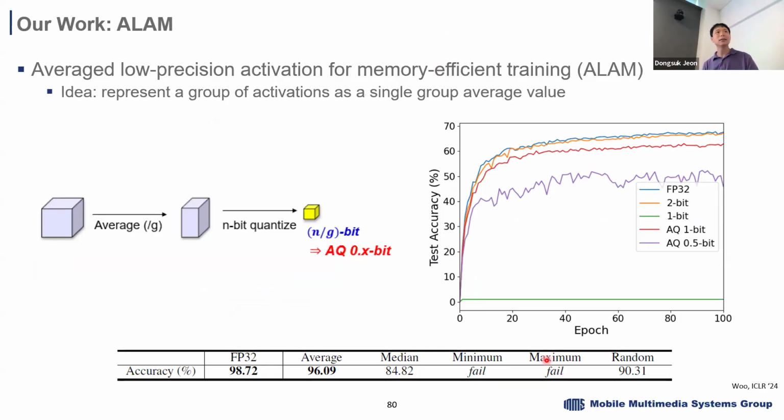The second question is, what's the precision for the intermediate result, such as a partial sum? In this case, we are using a GPU, so it's hard to tell. We don't know exactly what is going on in the GPU because they don't reveal all the details. But in our training processor ASIC chips, it was around 30-bit accumulation. That means the adder itself was actually 30-bit.